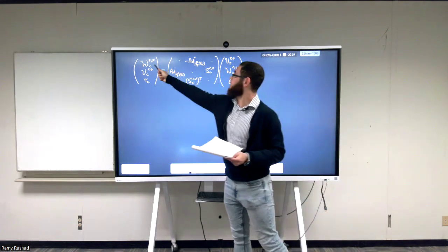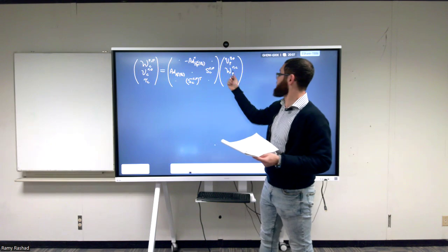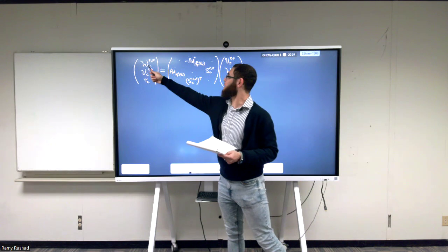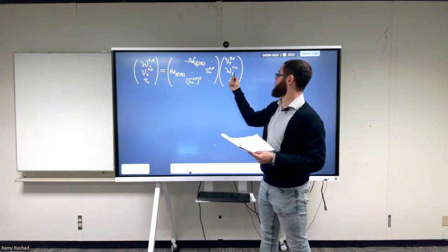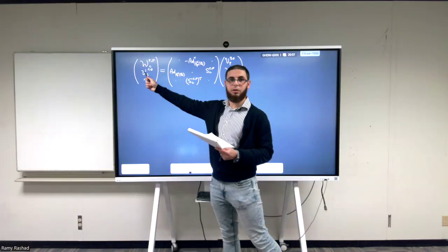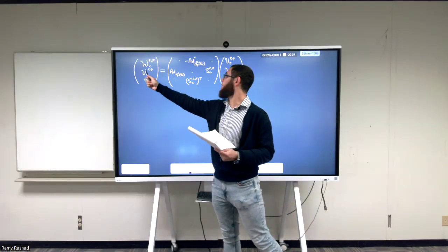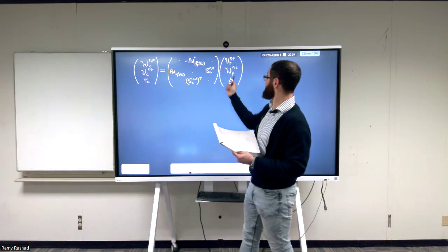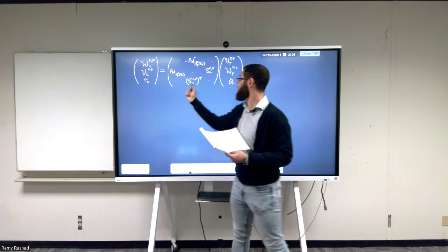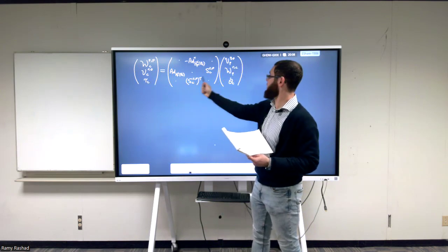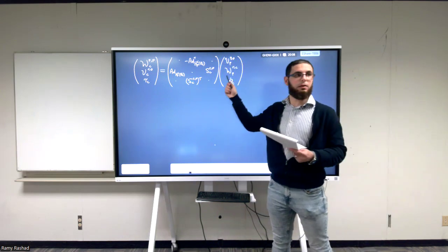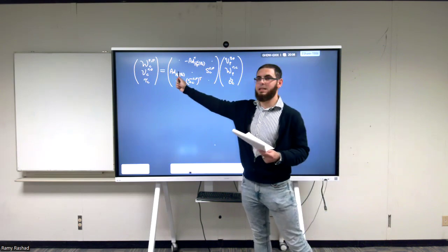So the first one simply says that it's related to this. All of these dots here mean zeros. So this wrench is equal to this expression multiplied by that wrench. This is the relation between the two wrenches we talked about. The child twist is related to the P twist and to theta dot by the second line. And the third expression says that the torque is equal to the transpose of the screw axis multiplied by this wrench.